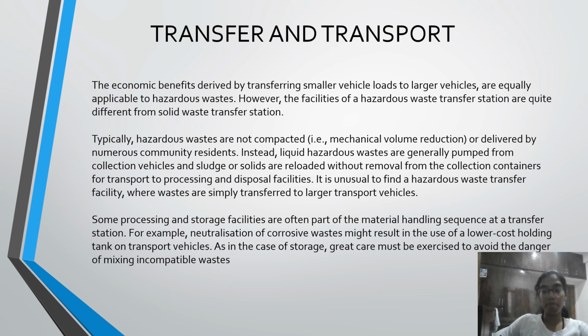They are generally pumped from the collection vehicles, and sludge or solids are reloaded without removal from the collection containers for transport to processing and disposal facilities. It is unusual to find a hazardous waste transfer facility where waste is simply transferred to larger transport vehicles. Some processing and storage facilities are often part of the material handling sequence at a transfer station. For example, neutralization of corrosive waste might result in the use of a lower cost holding tank and transport vehicles. As in the case of storage, great care must be exercised to avoid the danger of mixing incompatible waste.